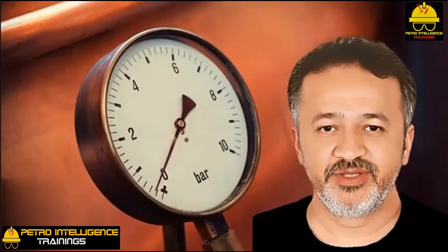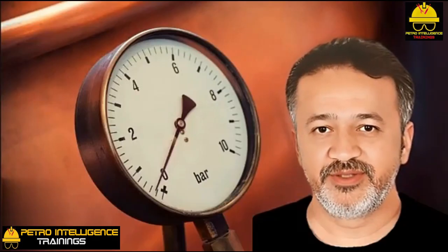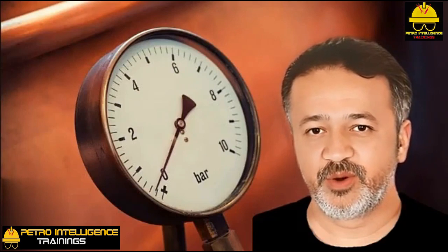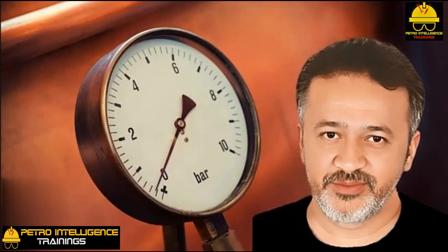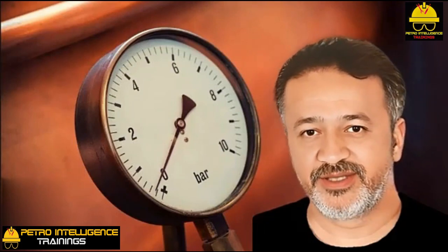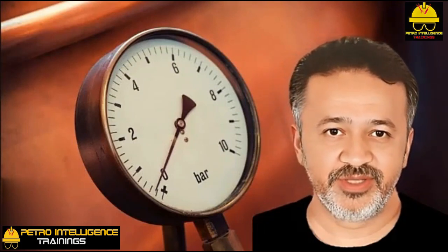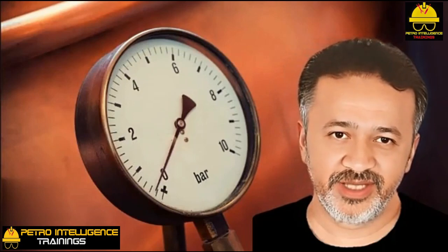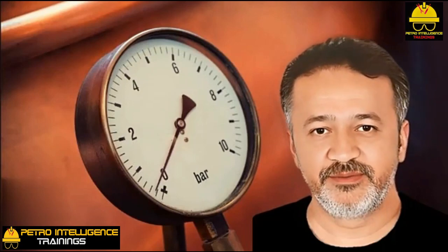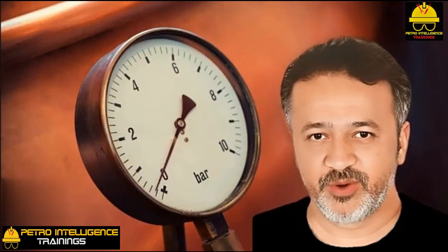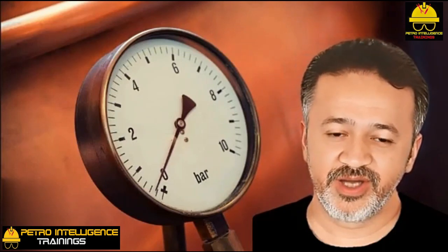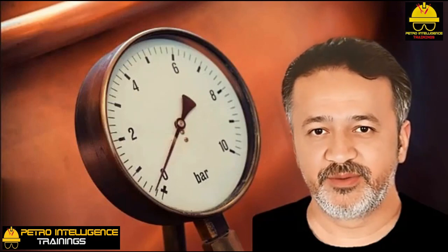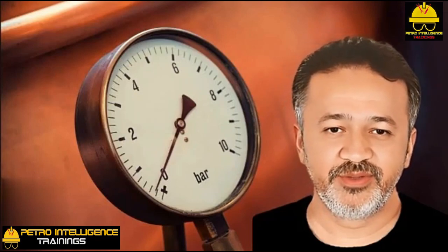Foam affects levels. Trying to predict a vessel level based on the output from the pressure transducers would work only if one knew the actual specific gravity of the fluid in the bottom of a distillation tower. But anyone who has ever poured out a glass of beer realizes that this is not possible. For one thing, the ratio of white froth to yellow beer is never known in advance. Also, the density of the froth itself is unknown and is quite variable.